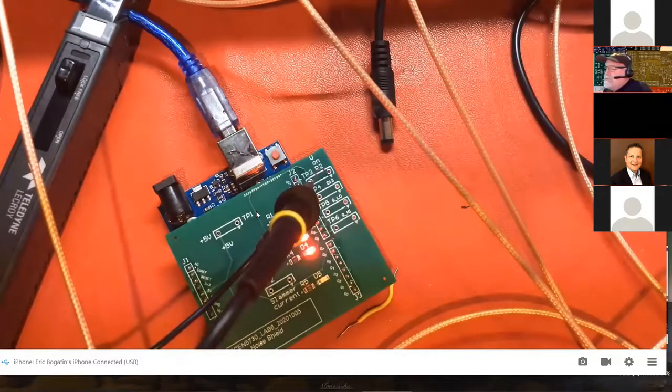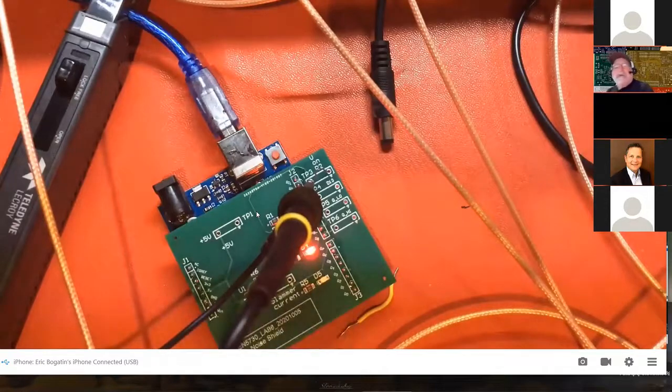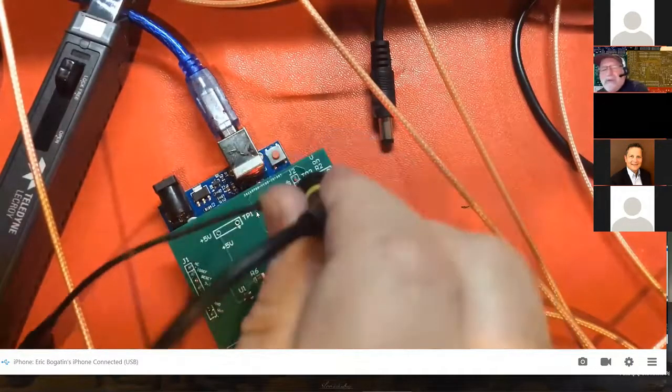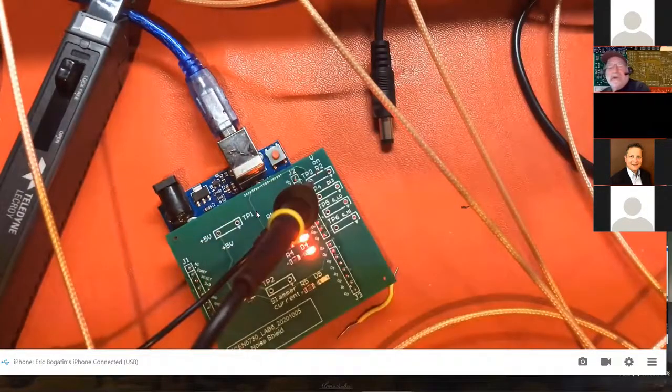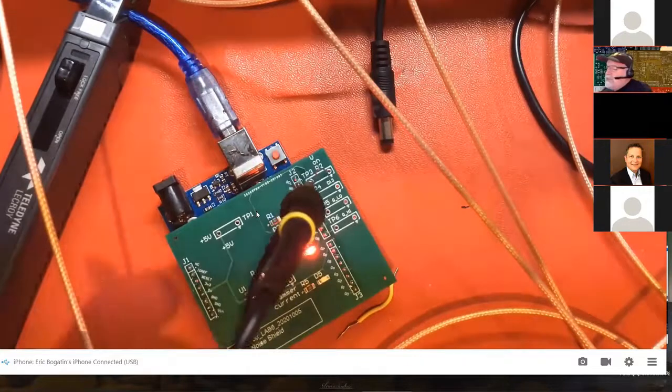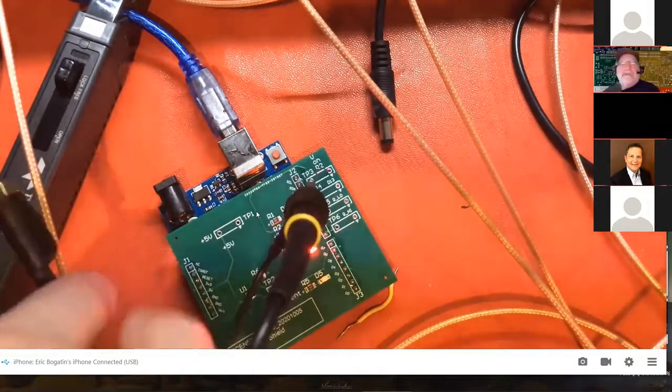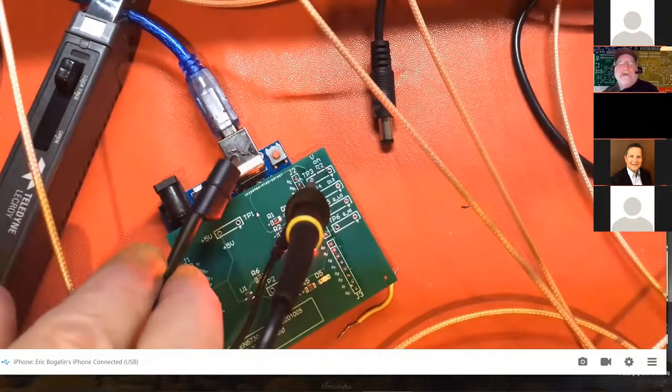And for these probes here, I think we demonstrated about a 300 megahertz bandwidth. When we have the spring tip, we generally get about a 200 megahertz bandwidth. And when you use the long floppy leads, depending on how long and floppy they are, the bandwidth is reduced closer to 100 megahertz or less.